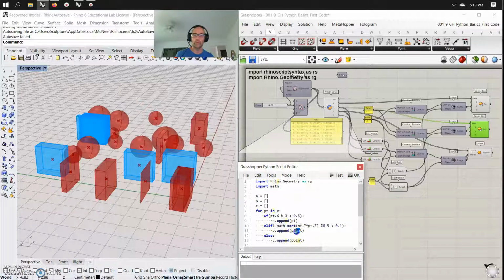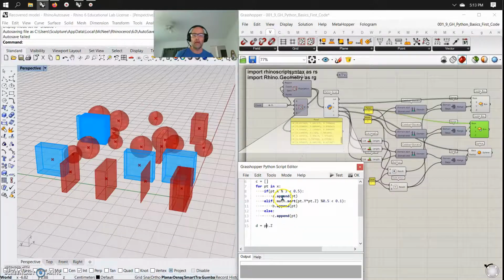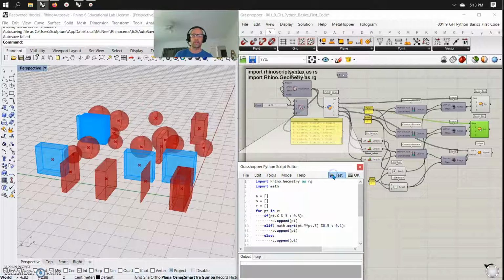But what I want to show you is with your variable, you can go in here, and I think I'll just have to change this one down here. You can still run that script. It should work fine. And there it goes. So basically, we weren't grabbing the attributes X, Y, Z of those points. And I think that's something we should have been doing earlier on. But this is the last step in importing point 3D in Rhino geometry.